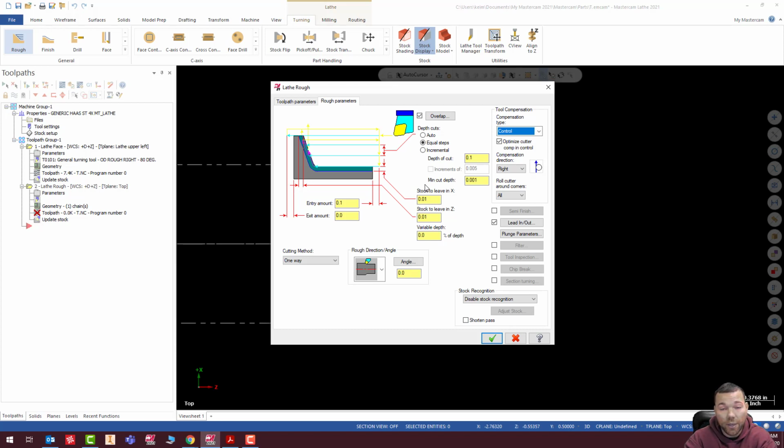If it's a 32nd, it's going to program the numbers so that it's offset by a 32nd, and so that any number that you put in your tool nose radius will just offset it further. It'll almost be like a wear inside your control.